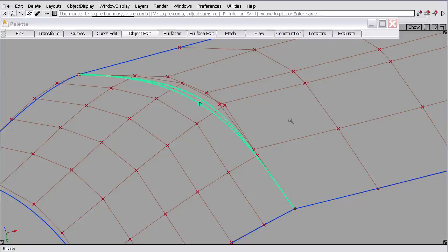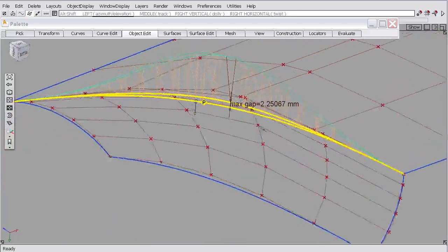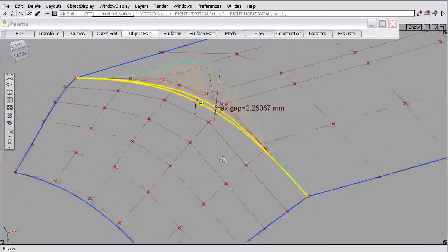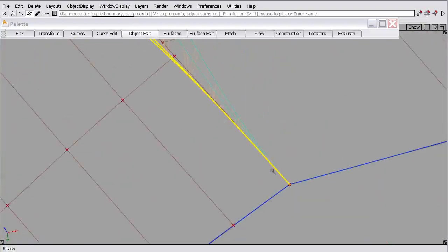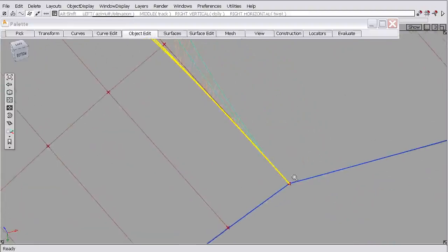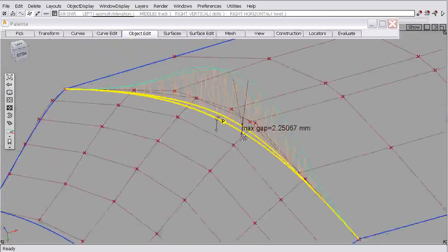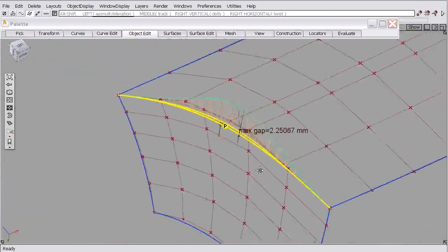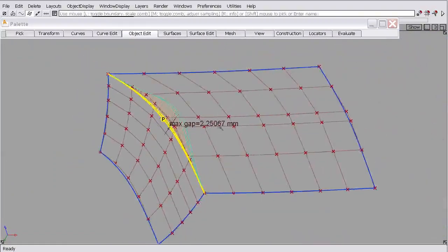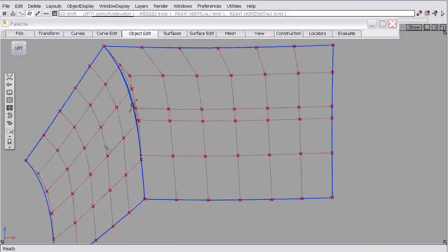So I can increase that number, and it goes to here 3, 4, 5 and on up to whatever I want. I usually increase it a little bit just to make a smoother comb, and set the scale to something that looks easy to understand. If we zoom in, the checkpoints are these little dots. So that's what show edge labels are. They're little dots along here that show where each point has been checked. Okay. All right. I'll delete that locator, and we can move on to the actual align function.